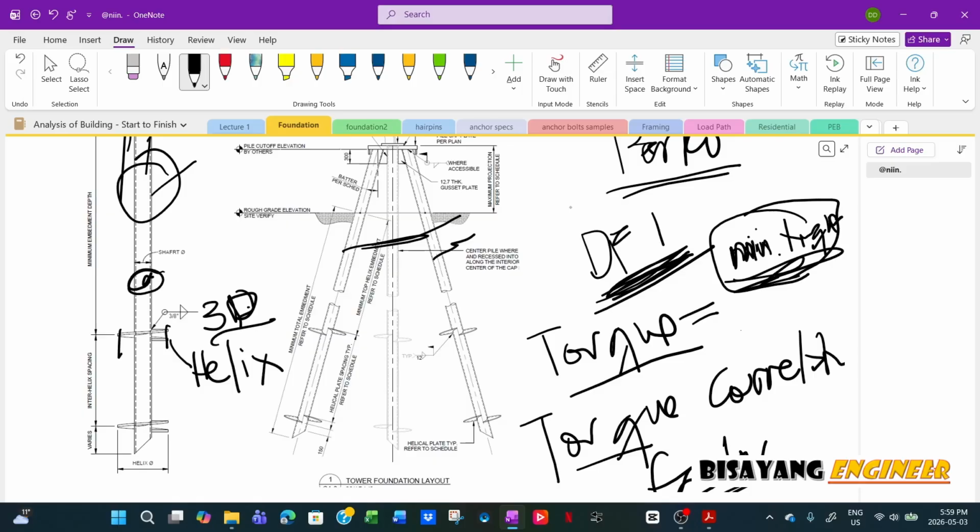Or helical plates. So the same. If in cast in place pile you space your pile three times the shaft diameter, this one is three times the helix diameter. And then it depends, either you will use the cylindrical shear on this one for the capacity, or the individual bearing plate. So if you are interested in this one, then you can buy that book by Perko,